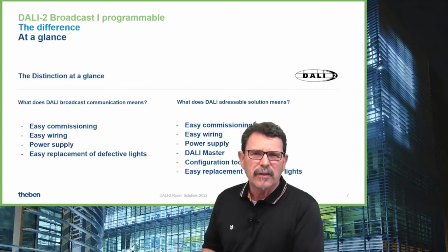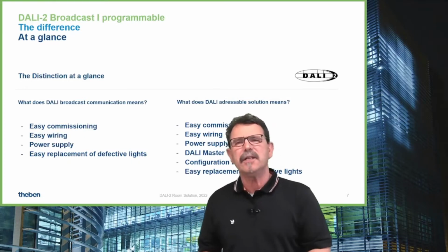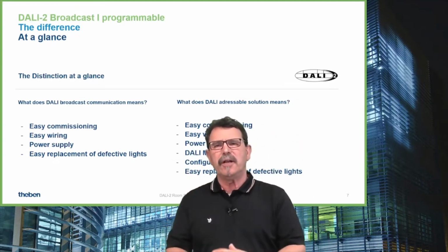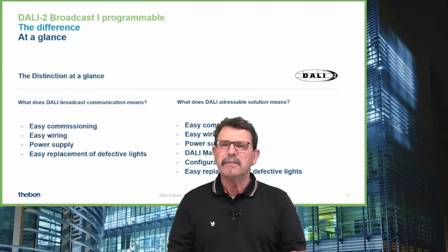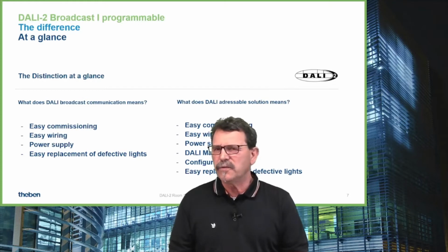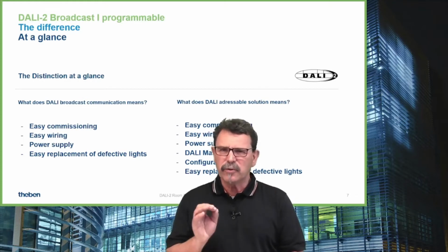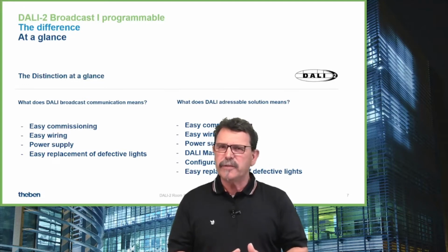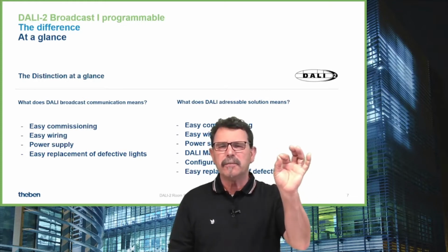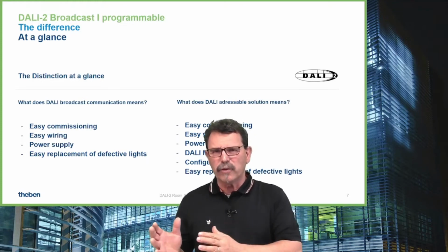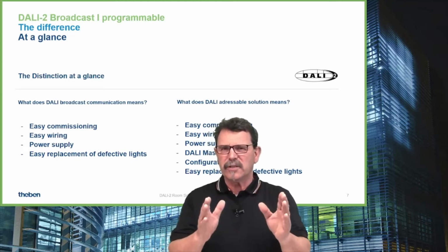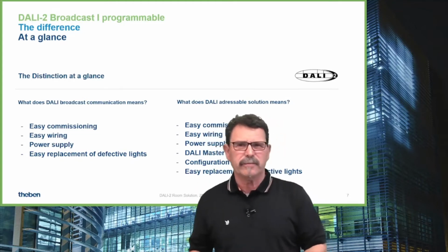Then, for the commissioning with addressable lights, you now have the choice to address each individual light in a room as a light group. You can use these different lights for a scene, to call up a scene, however. You can configure it, and for that purpose you need the commissioning process. You have to talk to each light: you are part of group 1, you are part of group 2, or whatever. And this is the difference to broadcast. Broadcast is meant for all. Addressable lights you can select however you like.